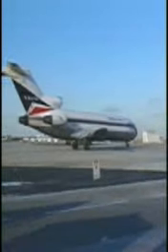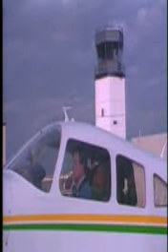There are several procedures that you can follow and precautions that you can take to avoid a runway incursion. Complete as many checklist items as possible before taxiing. Concentrate on your primary responsibilities. Do not become absorbed in other tasks or conversation while the aircraft is moving.